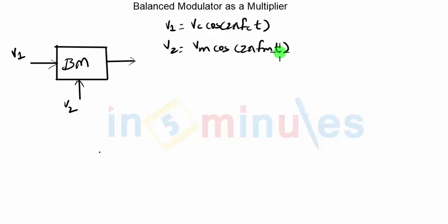If you recall that expression, you will observe that the main operation taking place in my final output signal was of this form. We had used a constant A and I was getting V2 on the output side in the form of the modulating signal. Please remember that this is not an important term. We in fact don't want V2 to come on the output side. We are only interested in the second term.